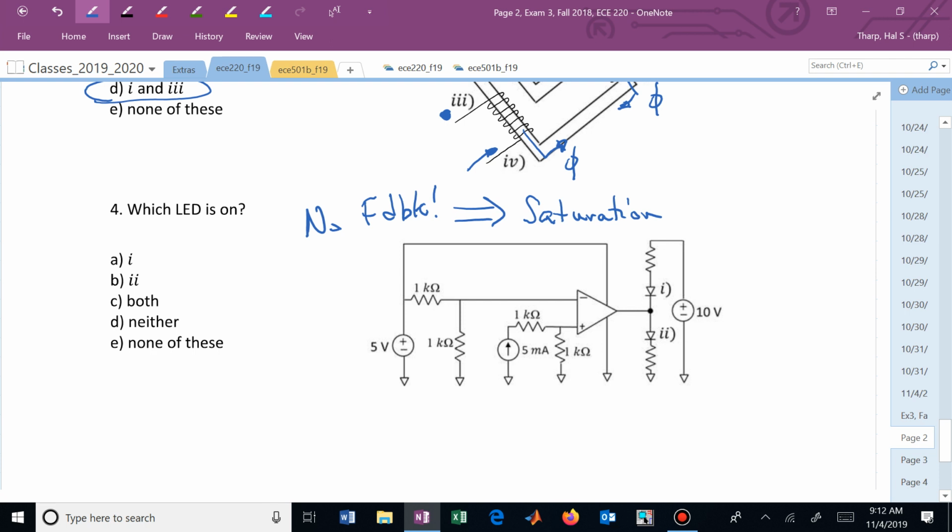And here, in looking at these previous exams with students before today, it could be a little bit confusing, but I think the notation has been that the power supply pin on the top is traditionally V+. Although if you looked at this in PSpice, this, I think, is an inverted op amp, and so the negative supply pin is probably consistent with the inverting pin on the op amp. Don't let that confuse you. Just assume that they are powering the op amp consistent with how it needs to be powered.